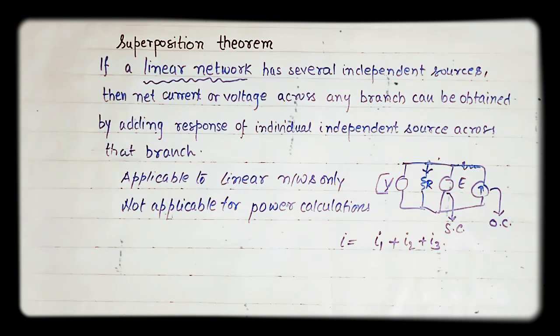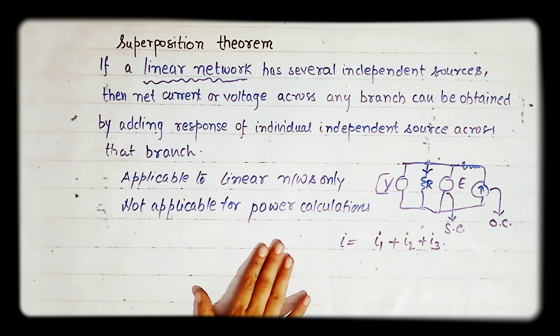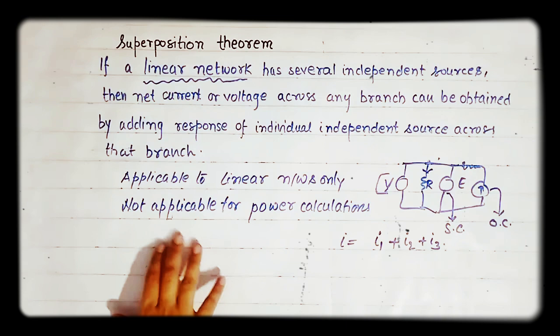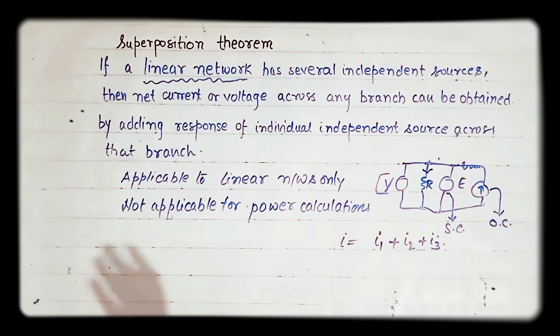Now I want to tell you that the superposition theorem can also be applied to circuits having dependent sources, but there you have to take caution. You have to keep the dependent voltage source intact. When I solve the question I will clear all these things, and you will get a better understanding of this concept when you solve the numerical related to the superposition theorem.